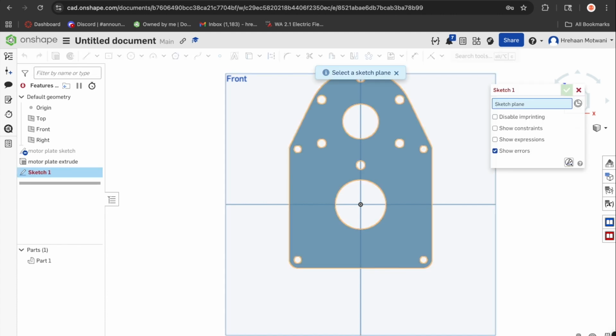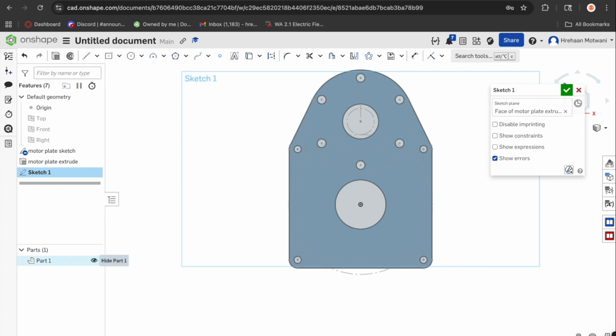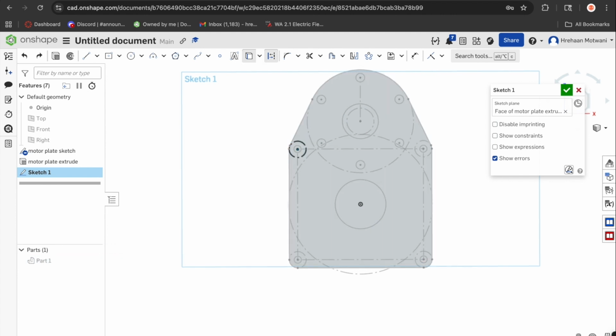Okay. And then we're going to create the second plate. So you would create the sketch on the first plate. Then you would pull up your first sketch, and you can hide your planes by clicking P, and then you can hide your first part here. We're going to do these as construction sketches, and the keyboard shortcut for that is Q. And then you're going to need these lines, so you would do that as not Q.